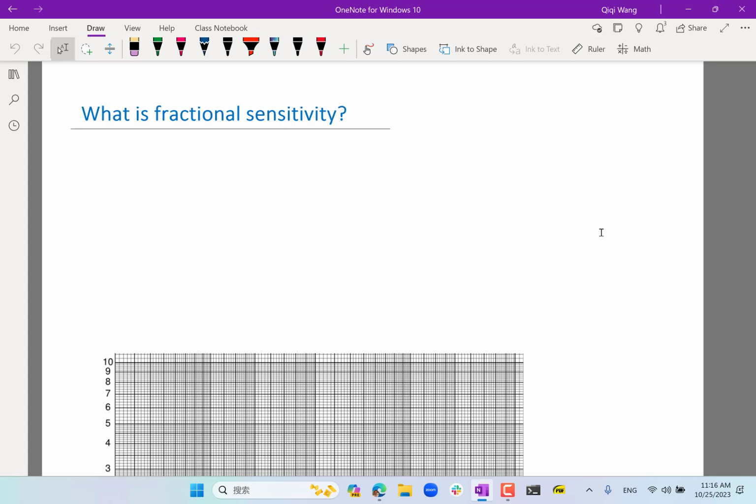So for example, a change in density is d rho over rho. If the density has increased by, let's say, 1%, then d rho over rho is 1%. If it decreases by 1%, d rho over rho is negative 1%. And we can also have dp over p and dT over T.